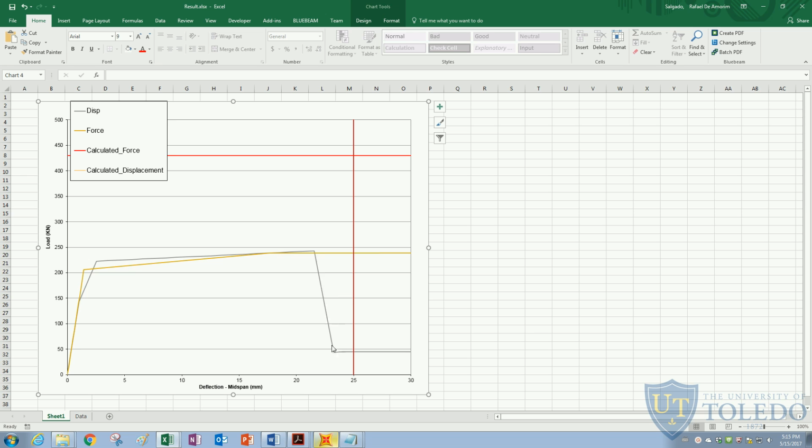Since this is a shear controlled beam and it fails in shear, the shear hinge is the main problem and the main factor which results in this highly conservative response. So we can conclude that the shear hinge that SAP2000 calculates by default is not very suitable for shear critical beams, and we should modify it, which we won't do in this video.